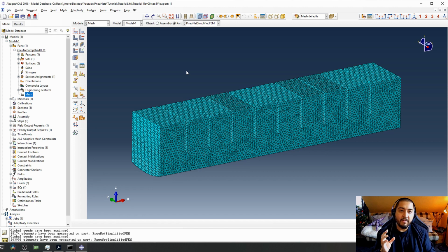And as I said in the beginning, it's not a good practice to try to simplify or to get faster results if you still have an accurate solution, or a more accurate solution, to take as a reference. If you can compute this, maybe it takes hours, but at least you know that it works. After that, you can decrease the mesh size and keep optimizing the solution time. But you cannot optimize something that you still don't have and still don't know.